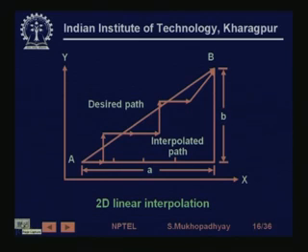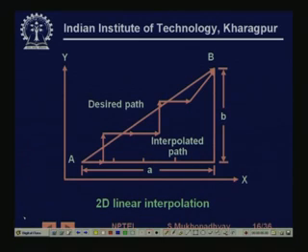So you see that this is a case where we want to have, let us say, this b by a. Now you see that contour is important. So it is not that we can first give a amount of x pulses and then give b amount of y pulses, because even then the final position of the tool is going to go from a to b, but it must follow this path as closely as possible. That is contour generation, right. So you see what is happening is that in the first interval an x pulse is given but no y pulse is given.